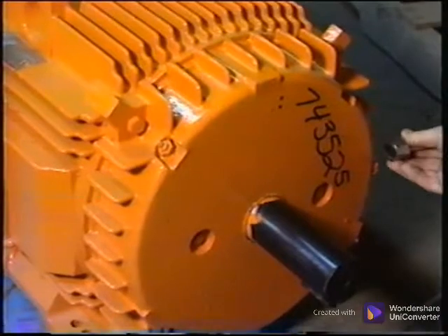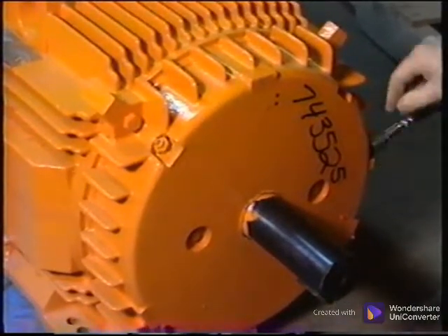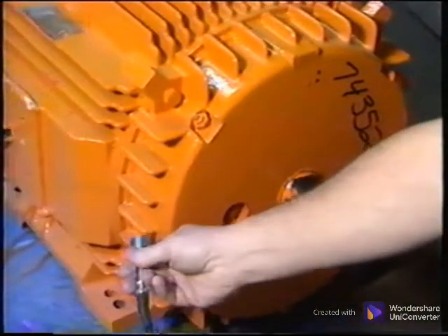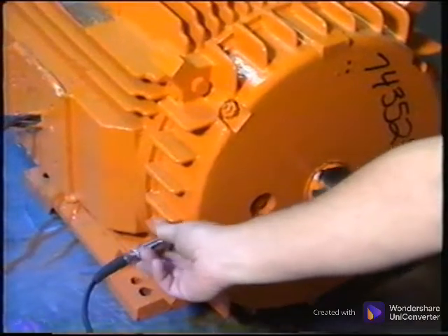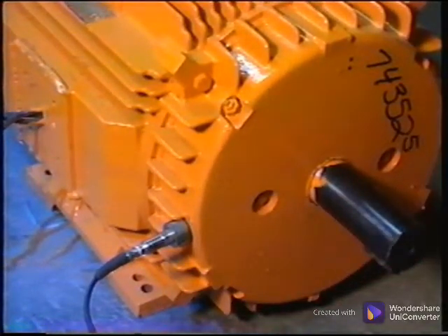Some suggestions should be made regarding the location of collection data points. A previous section identified the need for horizontal and vertical measurement at each bearing location, as well as at least 1 axial measurement per shaft. The magnet with 2 poles can be used on a wide variety of surfaces. If the machine has a smooth area, such as this one has, the magnet mount can be placed directly on it.